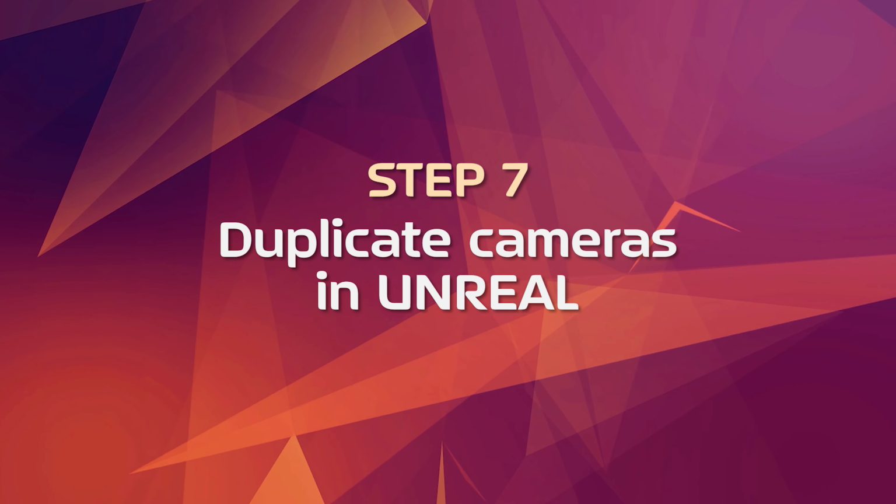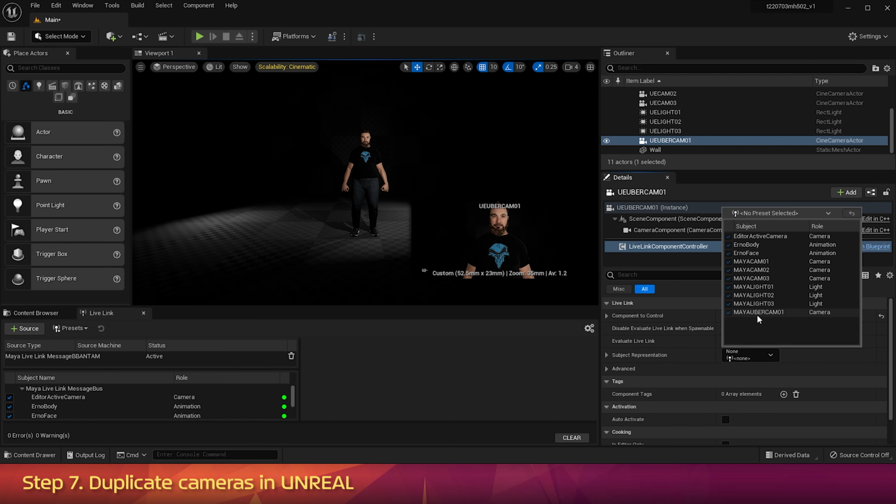In the World Outliner, click on UE Cam 01. At the top of the Details tab, click on the LiveLink component controller. And then under there, find the subject representation and change the drop-down to Maya Cam 01.